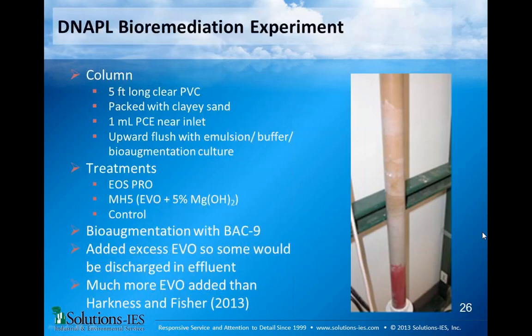If you add 100% of that magnesium hydroxide at the beginning, there is a possibility you add too much, and now you make the pH too high. Because if you add 1,000 pounds of magnesium hydroxide, and you don't produce the acid till a year later, you could overshoot. We have not totally solved the pH issue.